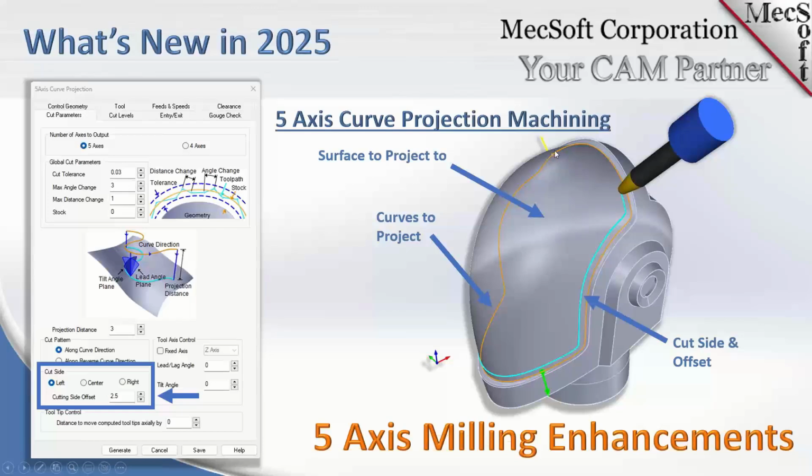If you tried to go in here and draw this offset curve, you would not get a good result because of the complex area this is in. Trying to offset it and then project it, it's going to be a problem. So you're probably not going to be able to use this method in previous versions. So now we do this as part of the toolpath. It's very, very helpful, as you can see in this particular part itself.